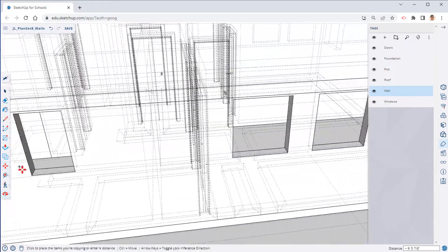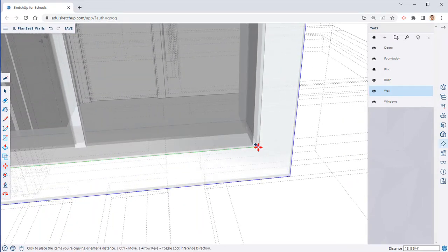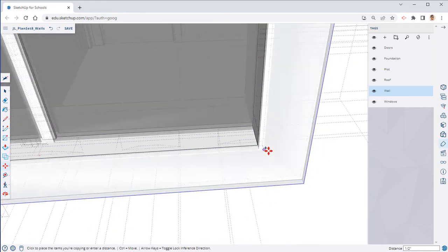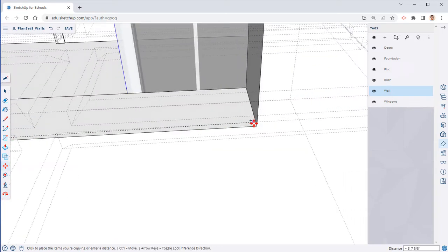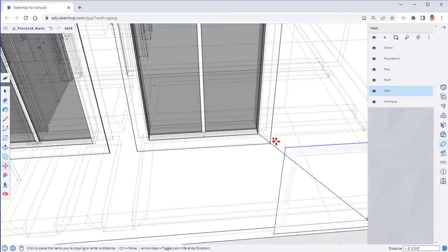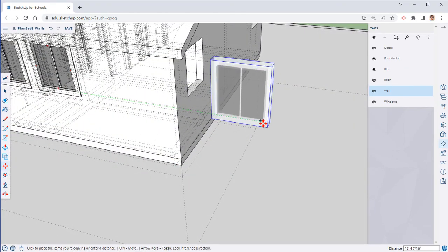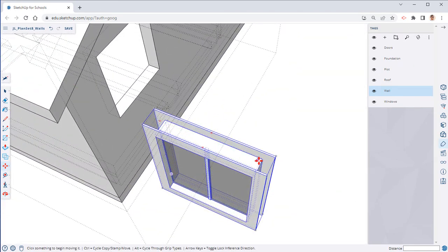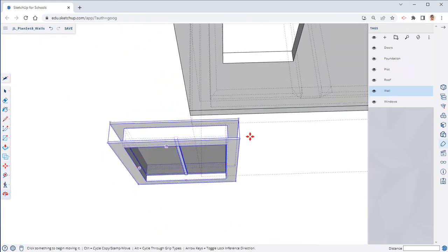Remember, whenever you're moving windows or any kind of shape inside SketchUp, you always want to go from corner to corner. That's your easiest way. It snaps those corners together, and if you don't do that, it will not snap together. And even though you can eyeball it close, it's not going to be the same. Here we want to just rotate this around using that move tool. Because it's a group or component, it already has those red X's.